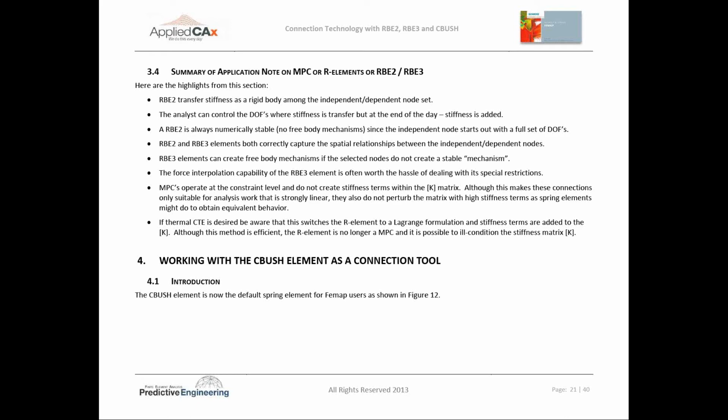Let's see here. The bolt heads are obviously the most common. Sometimes when you have linkages or pins or some sort of mechanism, you can get creative with which degrees of freedom you add stiffness to, and you can let it pivot one way but provide stiffness in another way. Yeah, lots. It's in every model that I can think of. Anything that I'm really idealizing, I have R elements within it.